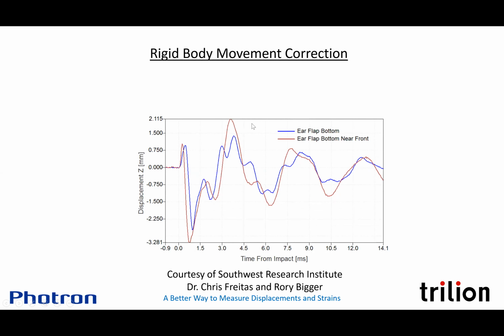Normally, though, we're taking a different approach. We're using the white light or the blue light, like I'm doing work right now on these high temperature load frames up at 1300 C. So the approach we hear about and do more frequently is we're going to do the white light DIC. We're going to combine that with an IR camera to get the temperature. And then we can get very fancy.